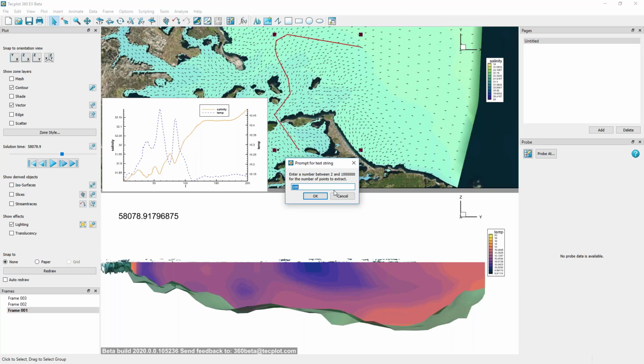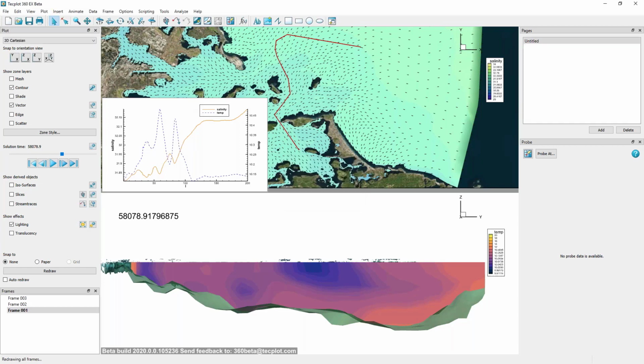The plot type you'll want to use to keep track of that is different than what I was showing here with the XY line plot type. You'll want to use a 2D Cartesian plot type, with a couple other steps involved, but you can show a similar plot style for the variable across that line over time when you do that type of extraction.